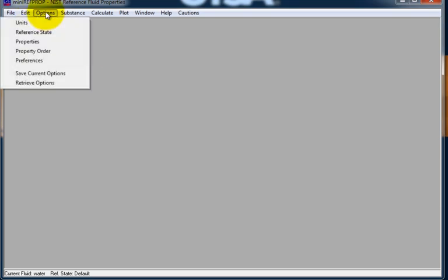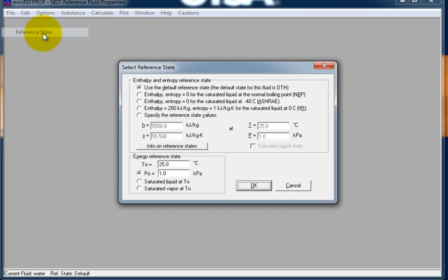Then also, you can talk about your reference state. Sometimes somebody will say, well, how come the value of the enthalpy from this software doesn't agree with the enthalpy out of the table? Often you trace it to the starting point for your energy measurements. Go back to Chapter 3 and look at that discussion, because that was a big discussion about how energy measurements all have a reference point.